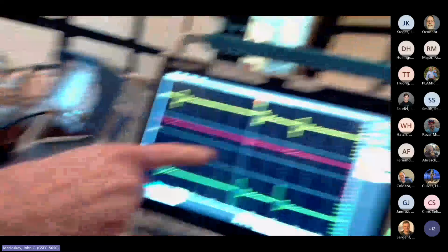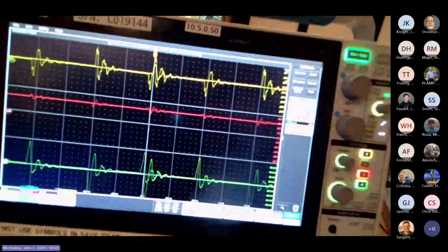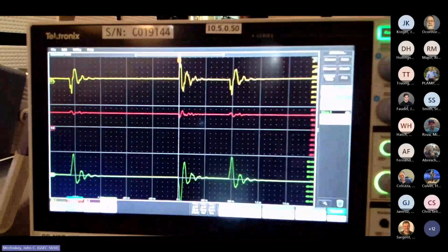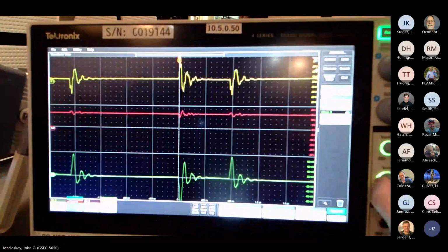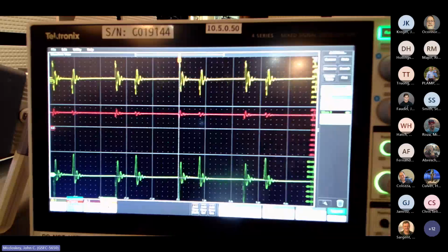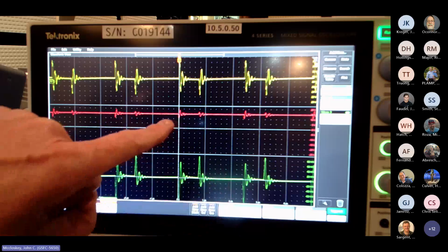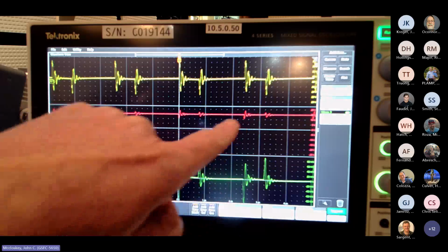So now we're not getting the bouncing anymore, but we are still getting significant noise and ringing at the transitions. Those are the switching transients from just the action of the switching power converter. Recall this thing is operating at about 400 kilohertz, so about a 2.5 microsecond period. It's at 1 microsecond per division, so that's what we're dealing with.